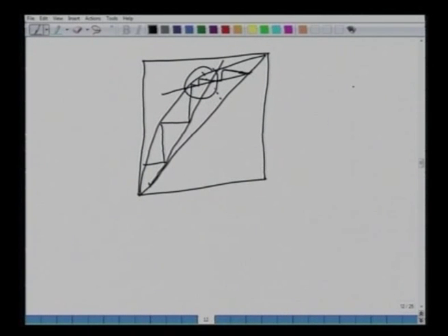If you like to expand this here, we have the two operating lines, we have this Q line here, and if you start from say xd, come to the equilibrium curve, then even if you have gone past this Q line, one can keep on marching on this equilibrium curve till after some time, you can reach almost the point of pinch, and then you can come down to this second operating line.